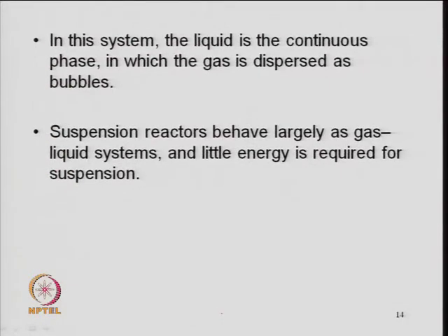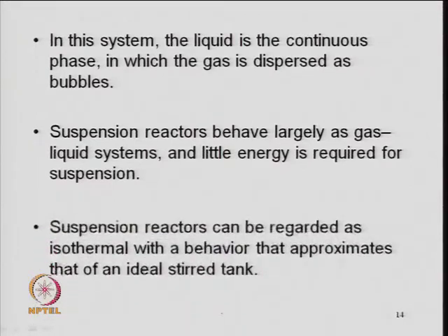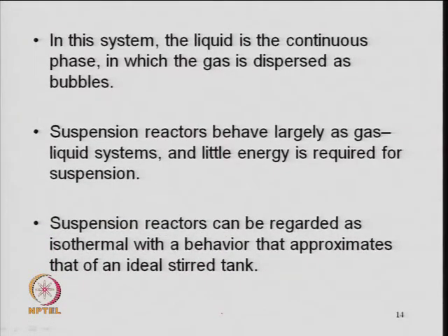Some advantages in this system: the liquid is in the continuous phase, in which the gas is dispersed as bubbles. Gas bubbles are coming from the bottom and liquid is already present along with the solid. So liquid is the continuous phase and gas is dispersed in the form of bubbles. You will have small gas bubbles. Now you need to design a better sparger so that the bubble size is controlled, otherwise the mass transfer resistance will be an issue.